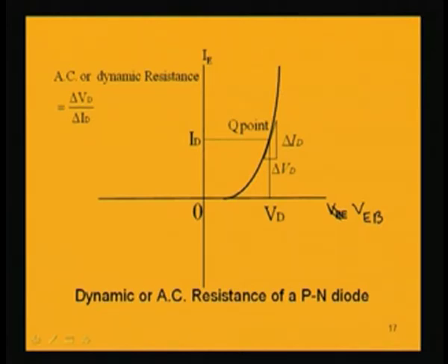So, if we now consider the dynamic resistance, it can be found out around this operating point, that is the DC biasing point actually, that is the current which is flowing, the DC current is IE, and we are finding out this dynamic resistance by finding out the slope del VD by del ID, VD and ID, these are the diode voltages and currents.